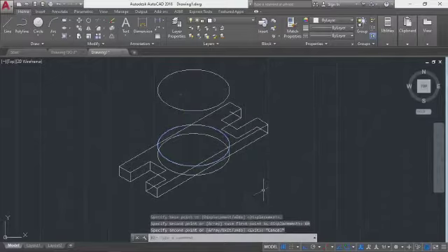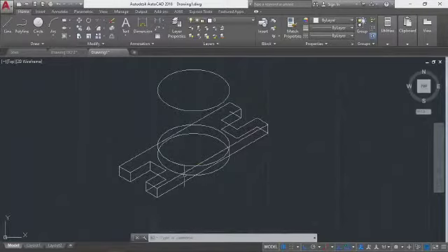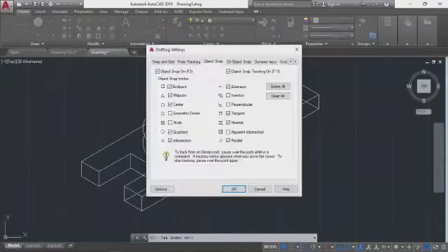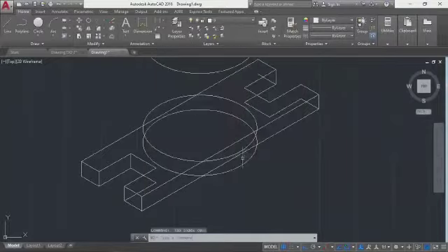Then what will I do now? The next thing is to join. There are some lines that intersect. To join them together, I'll go back and pick line and join these points where there is an intersect. You see, it's not showing. It's not bringing out the cursor because I have not picked intersect on my toolbar. I can come over here and pick intersect, and on the object nav, I can come and pick intersect. Intersection is there. Okay, let me click OK and come back here. You see intersect. You're supposed to highlight it as intersect.